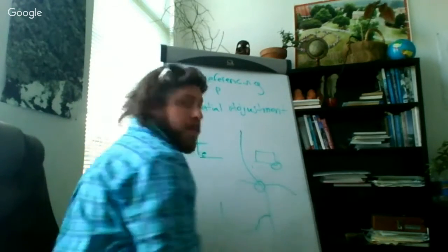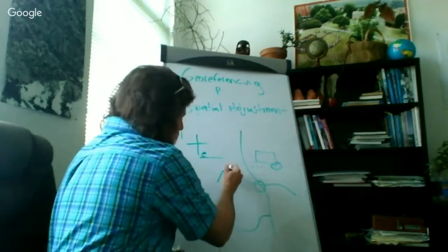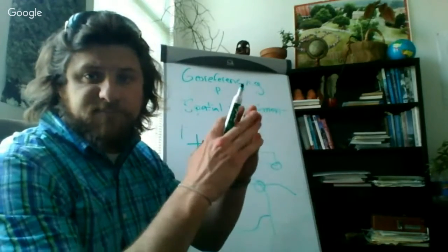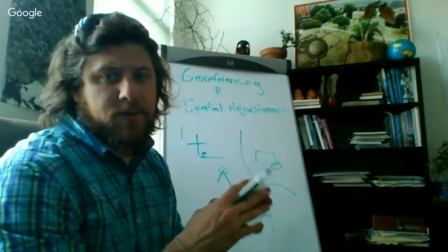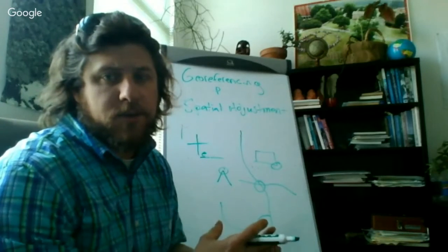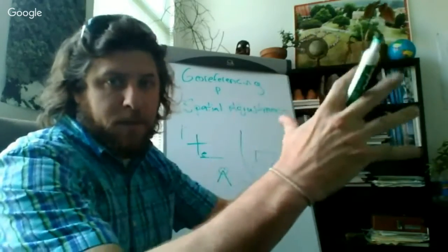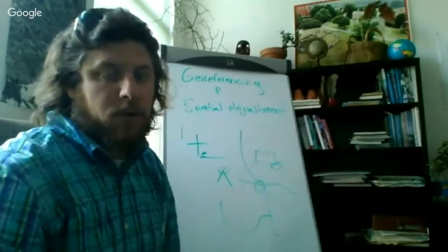Or maybe we pick the corner of a building or some sort of easily identifiable peak where we have very distinct features. And basically, to do a georeferencing or spatial adjustment, you need a minimum of 3 of these so that we can fit one data set into the grid of another.